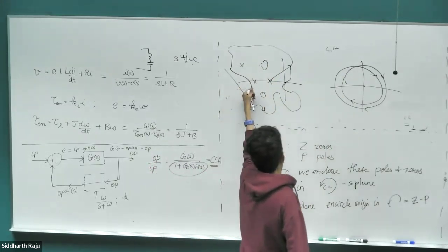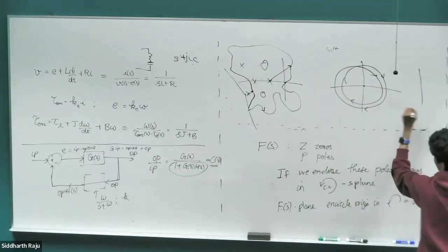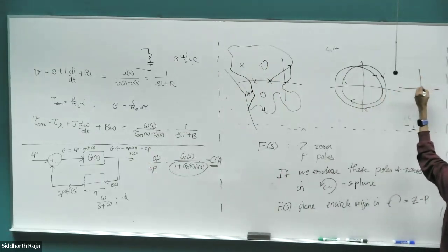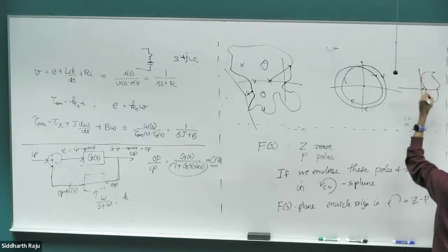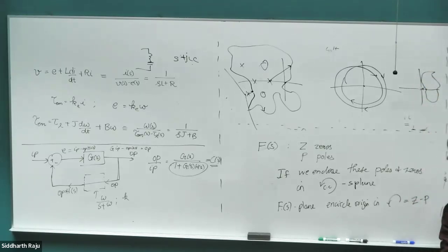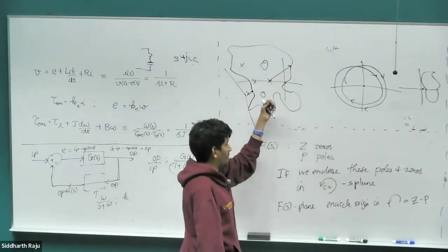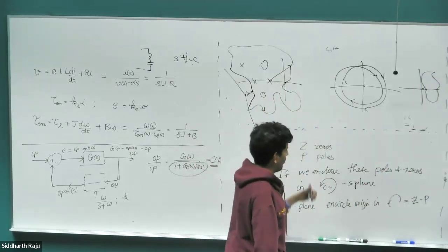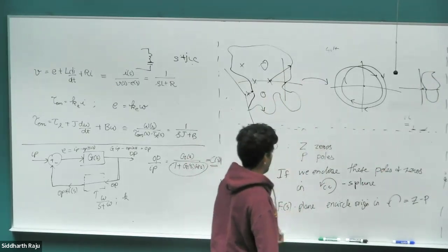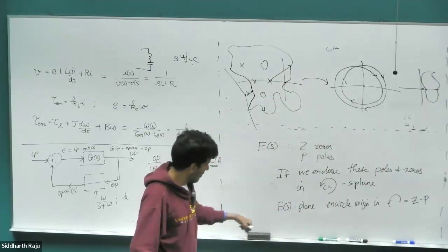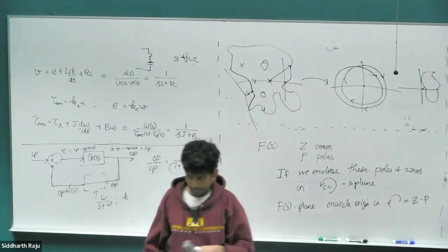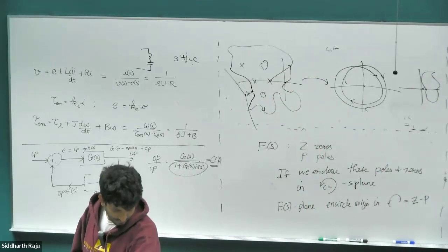So when you map this vector onto this plane, just for that particular loop alone, you would end up having some kind of loop that would end up looking like this, right? It wouldn't go through the origin, it wouldn't enclose the origin. But if you had something within it, whenever it does the full loop, it does the full 2 pi, so it would end up being a circle on the other side, right? That's all the whole proof is in essence. Okay, so let's try and see if we can figure out stability of a system.